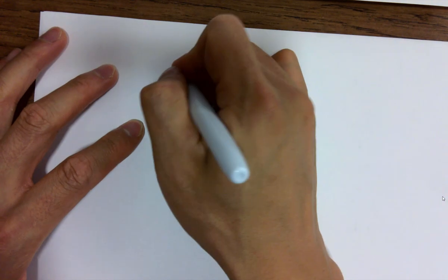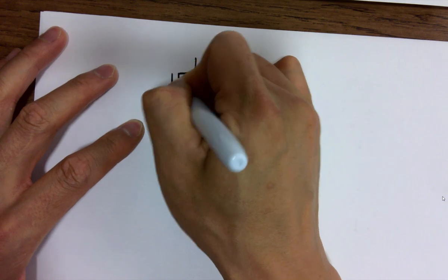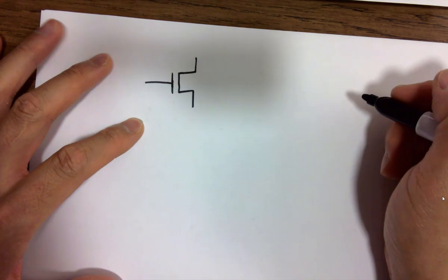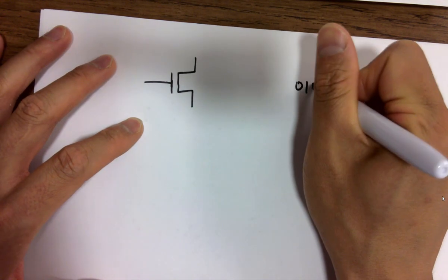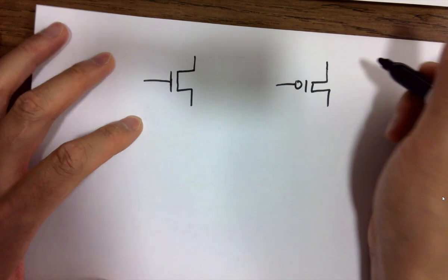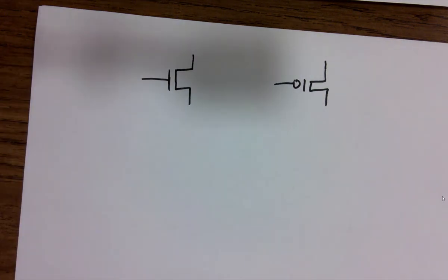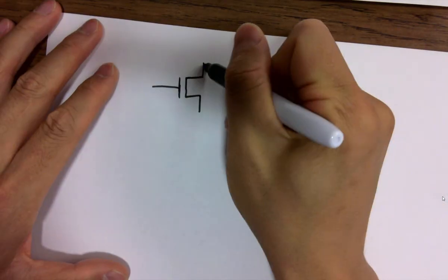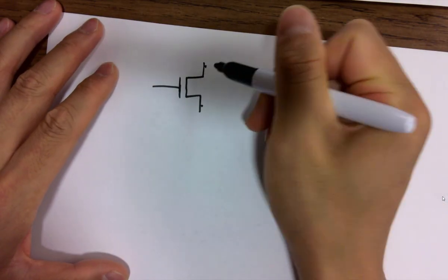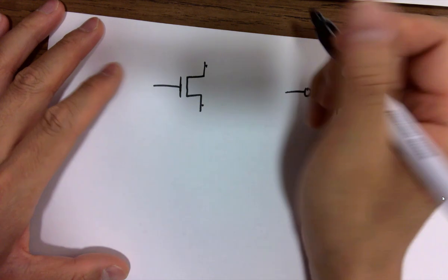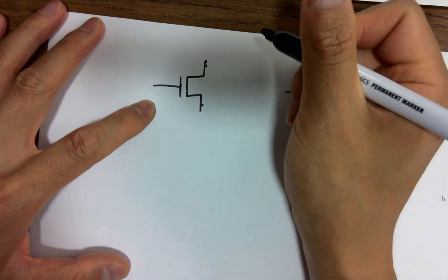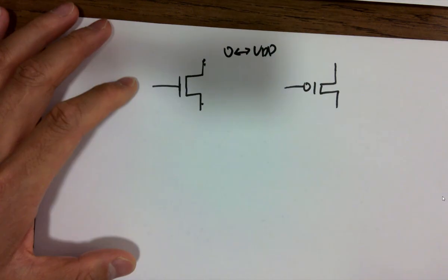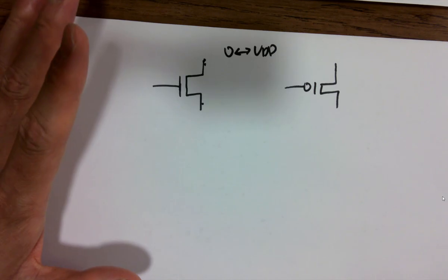So now let's talk about another important concept here. Like I said, the PMOS and NMOS transistors are symmetrical. You can tell from the layout. You did it in the lab. From left to right, there's no difference. Diffusions, vias, no difference. So in that case, you can treat this as D, this as S, or vice versa. Doesn't matter, okay? For digital signals, there are only 0 and VDD. There are no other voltages. Digital voltages, 0 and 5, or 0 and 1.